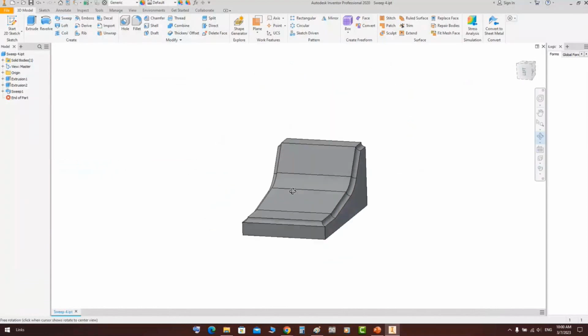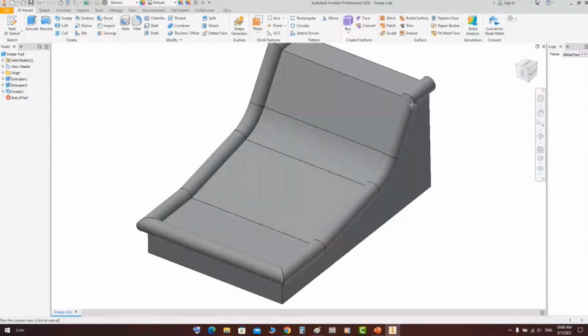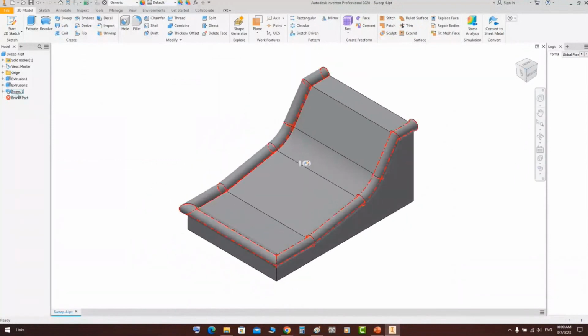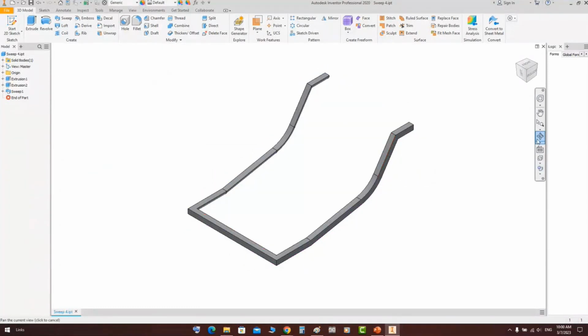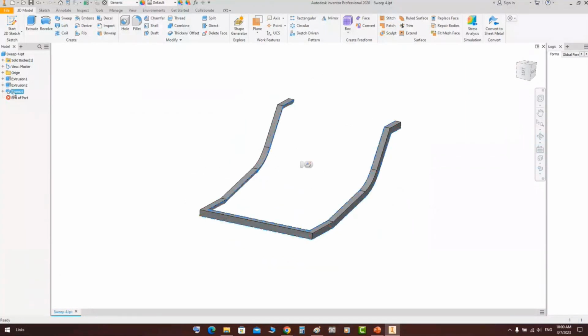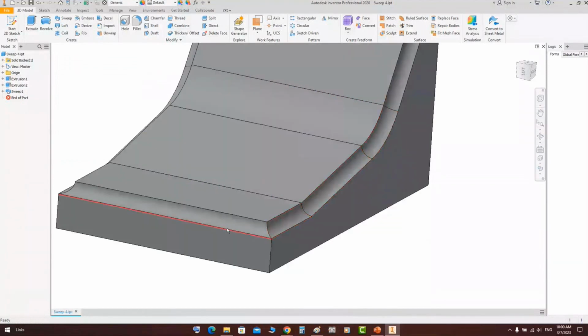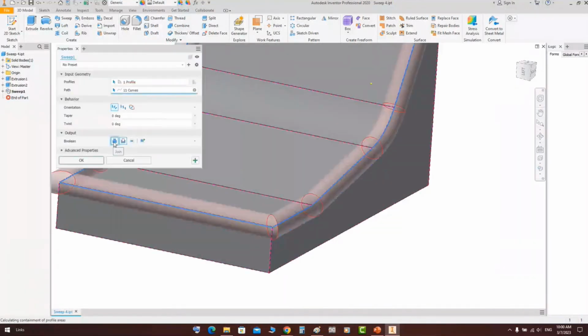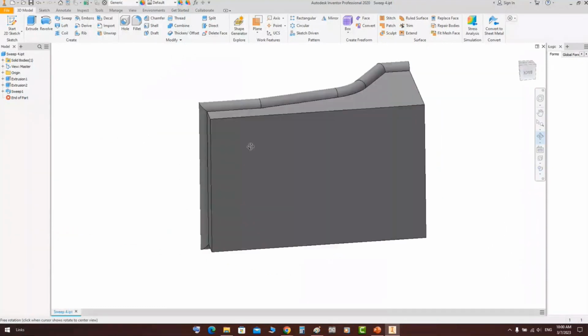by extrude. So you can make it as a cut. We come back here, you can make it as a cut or as a join part. As we discussed in extrude and revolve, you can make it as a solid or a cut or intersect. With the intersect, you can get the intersection between the two parts like that, or you can make it as a cut. So you will make a cut like that, or you can make it join solid with the previous solid like that.